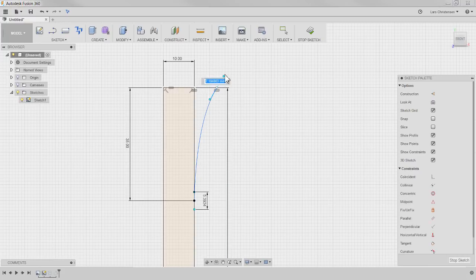Same thing with these two handles up here. They would need a dimension that was running parallel. It will need a dimension like this, but it will probably also need an angle dimension like this, and then we probably also need a dimension from the width here. Now you will see it's finally fully defined. You can definitely do that, and a lot of people will tell you that the right way in CAD would be to fully define splines.